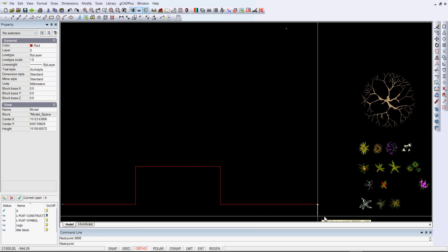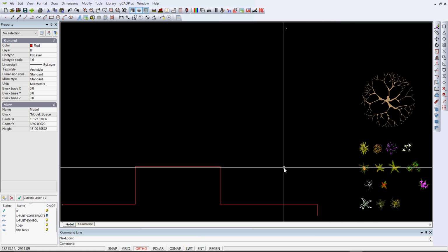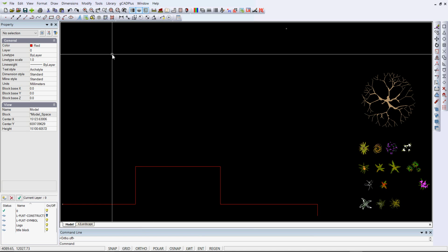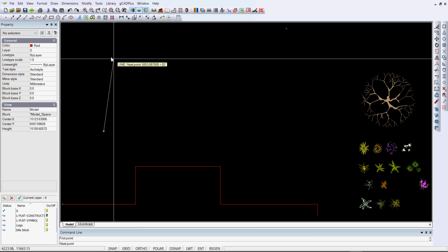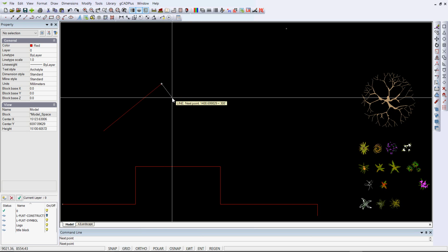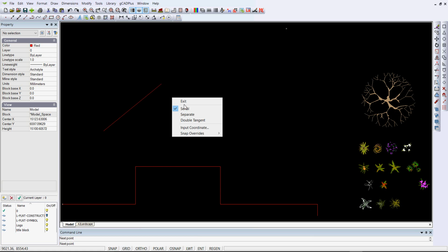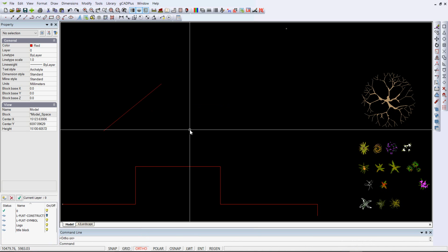and enter. And to get a little bit of the side wall, just click anywhere you like and then right click and exit. At this point I might take off ortho. Let me use the L shortcut and enter for line and click a line. Can you see with the ortho switch off I can draw in any direction, right click and exit,